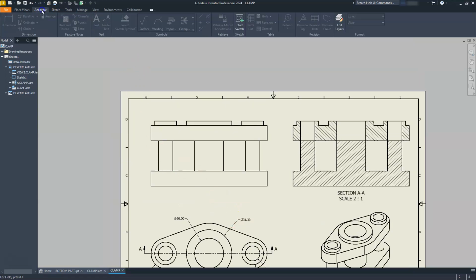Let me jump over to the annotative tab here. Go ahead and put some center lines on here. So I want to go from here. And I was thinking that I can get to that center there, but I can't, so I'll go ahead and use the bisecting ones. The bisecting ones are good. Sometimes they're a little bit better, but I have to manually kind of extend these lines out. So it takes a little bit of my control away.